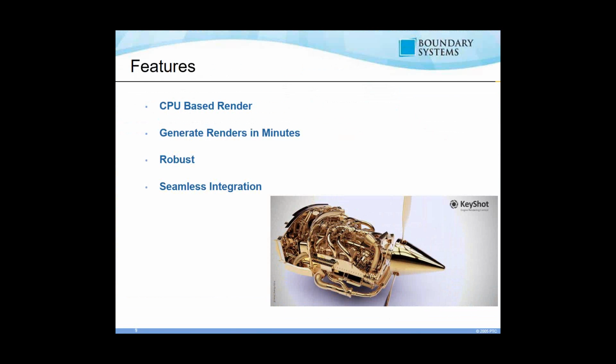it's pretty much linear in scale. So, if a good quality render takes you, I don't know, say for example, 20 minutes on a 2-core machine, with 4 cores, it'll take 10 minutes. With 8 cores, it'll take 5 minutes. With 16 cores, it'll take 2.5 minutes, right? So all of a sudden, you begin to see how with just scaling the CPU cores of your machine, you can dramatically improve your render performance, right?